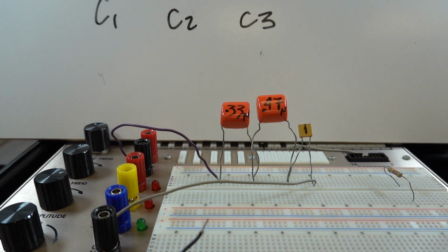I know in the laboratory it talks about specific physical characteristics of the capacitors, but capacitors come in all shapes and sizes and different colors. So you'll just need to make sure you look at the notation from the manufacturer, and then use your digital multimeter if it has a farad meter, or a separate LCR meter, to measure the actual capacitance of those particular capacitors, so you can assure that they are correct.